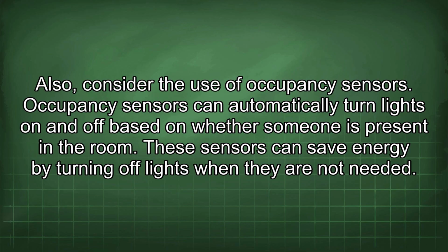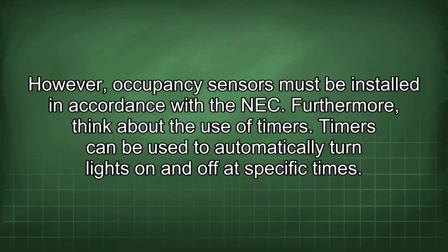Also, consider the use of occupancy sensors. Occupancy sensors can automatically turn lights on and off based on whether someone is present in the room. These sensors can save energy by turning off lights when they are not needed. However, occupancy sensors must be installed in accordance with the NEC.